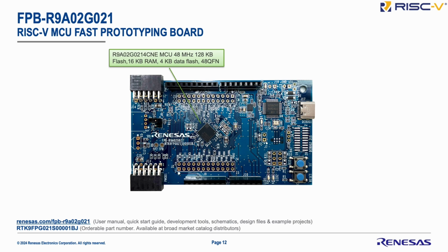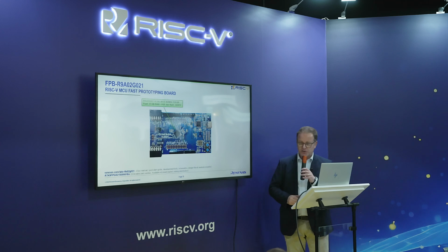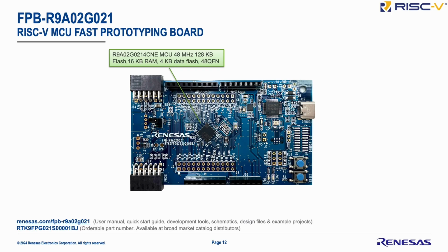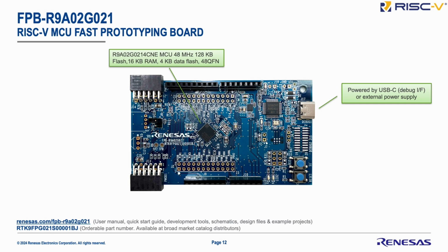This is basically usable similarly to an EEPROM, so it's essentially an on-chip EEPROM that you can use for data, and is a 48QFN package. The board is powered directly by the USB-C interface connector, or if you want, you can also use an external supply. If you want to test the environment at a different voltage level, you remember it can go from 1.6 to 5 volt.